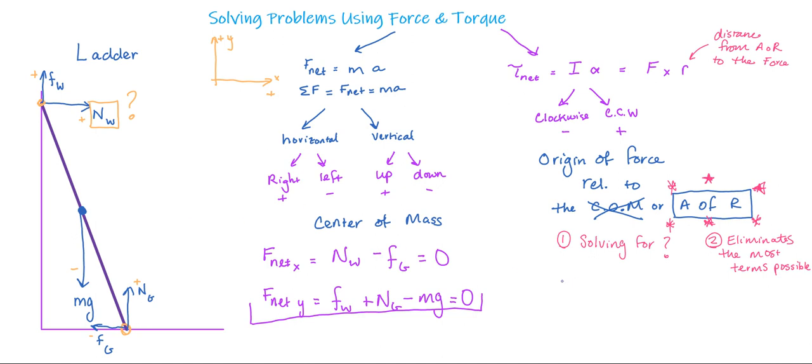So what I'm going to do here is say that my net torque statement is going to be equal to each of these forces times their position times the angle at which they're acting. Okay, so here's my pivot, meaning this force and this force are not causing a torque. Don't have to worry about those whatsoever. Okay, so I'll start up here. Now, instead of doing positives and negatives based on what direction they're pointing, I'm going to choose positive and negatives this time to decide what direction that force would cause the object to rotate, counterclockwise or clockwise.